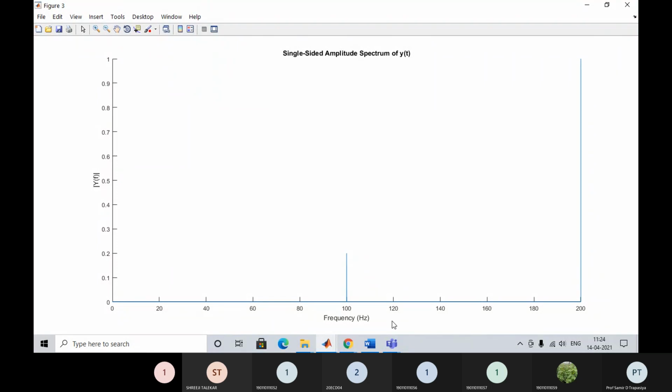So this graph is useful to understand the frequency composition of your signal, and along with this the amplitude. Individually you can identify which frequency component contributes more to producing your signal and which contributes less, and you can even find how they are scattered around. You can find the scatter diagrams of these frequency components, identify each component with its magnitude, and even do bandwidth analysis using this. That is very important for you.